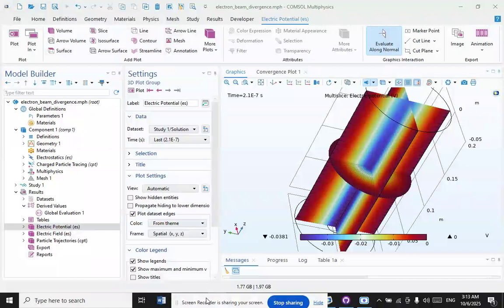Specifically, the role of electron beam divergence and the location of the beam focal point within the substrate is numerically investigated. It is shown that the location of the beam focal point directly influences the keyhole formation dynamics and leads to drastically different keyhole structures. It is further shown that a less divergent electron beam has a greater penetration rate and produces a more stable thermocapillary.